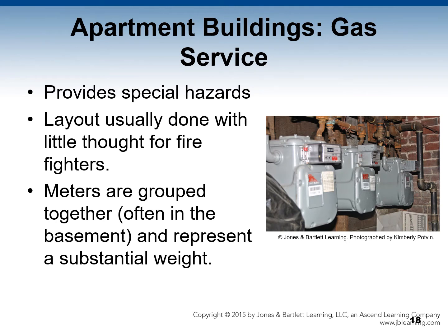In regards to natural gas service to apartment buildings, natural gas provides special hazards in these types of structures. The service layout usually involves little or no thought for the safety of firefighters, unfortunately, and meters are typically grouped together and represent a substantial weight, which means that's weight bearing on a wall, which is subject to collapse.